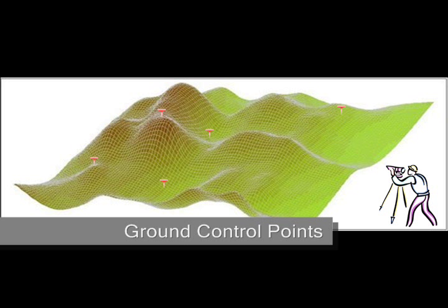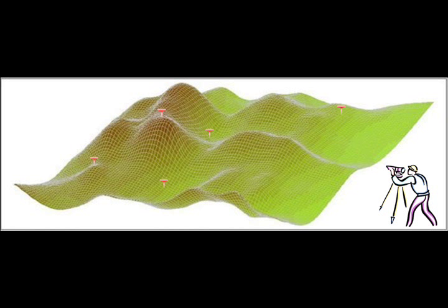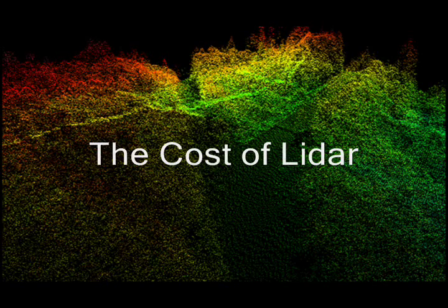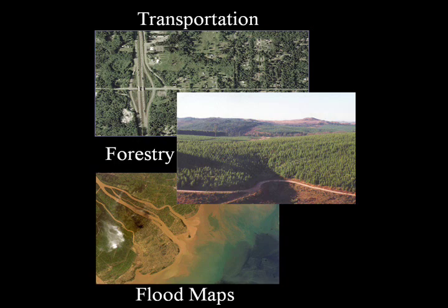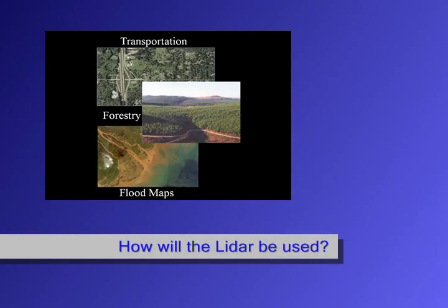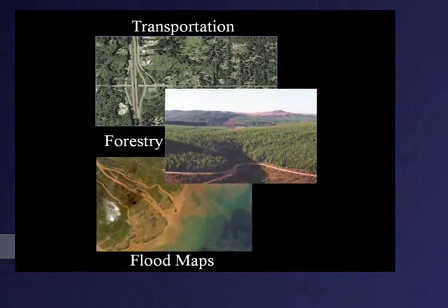To determine if the LiDAR data meets the required quality specifications, control points are assessed in the project area and compared with the LiDAR return values. Because of the many varieties of LiDAR data, products, and applications, its cost may vary significantly from project to project. The most important question regarding LiDAR's cost is how will the data be used?